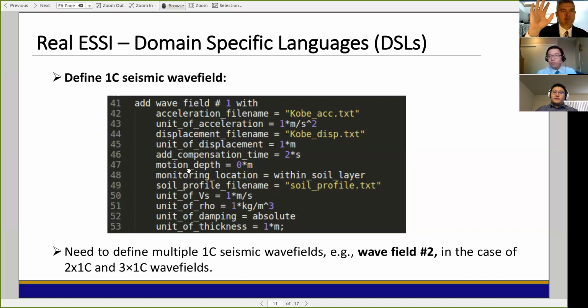Essentially, you're predicting how early you should start so that the wave actually has time to propagate. Depending on the shear wave velocity or P wave velocity, and depending on the depth of your model, you can make an estimate here. So 2, 3, 4, 5 seconds. It doesn't hurt that you're just adding zeros, and it really helps, because then you get the proper waves that start from 0, and then they slowly propagate and start exciting the surface system.